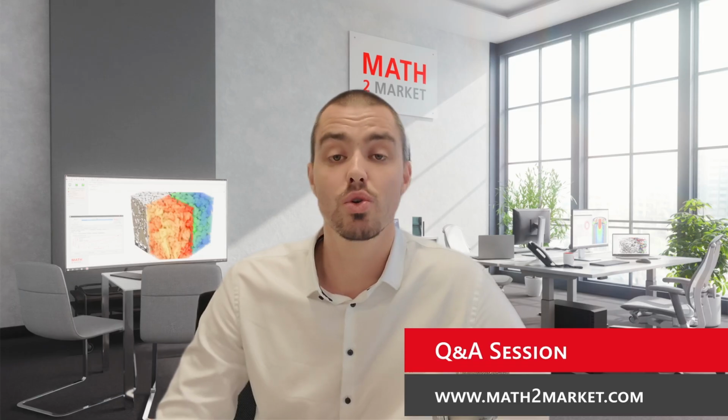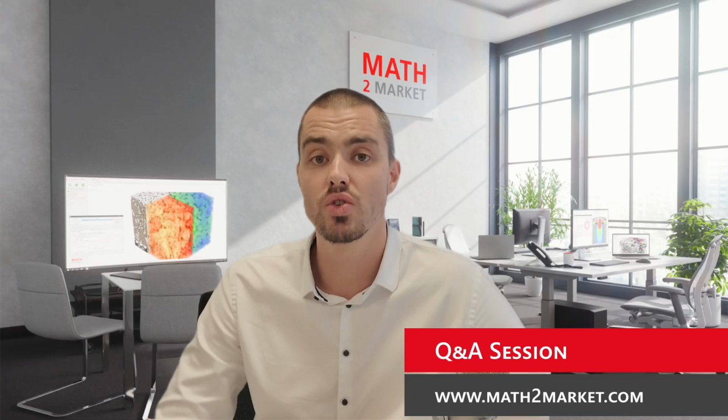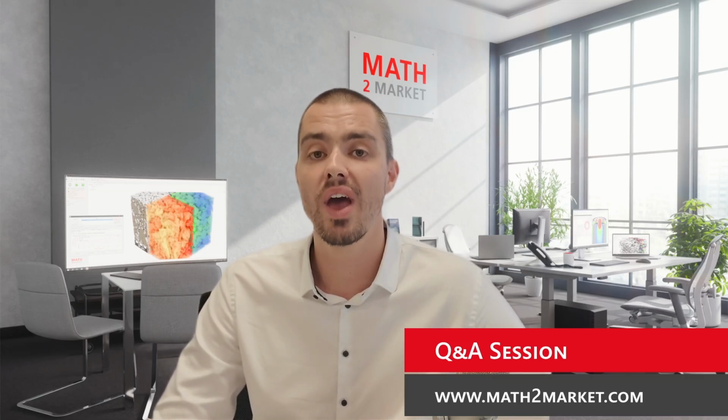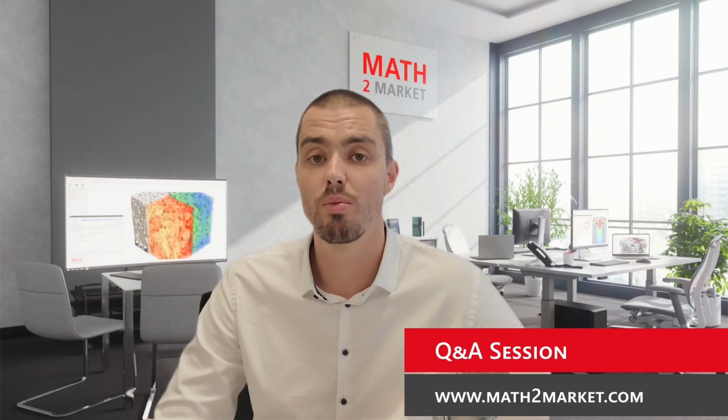In this case, what could also be used, and this is more relevant for clastic rocks, so the ones that are based on the grains as the building block, so to say, we could also in GeoDict directly generate the digital twin based on, for example, the experimental grain size distribution. So if you have a grain size distribution available, it can be used for generating a digital rock model directly in GeoDict as well.